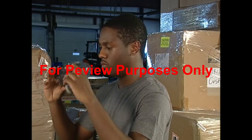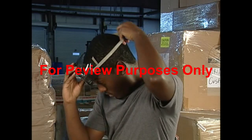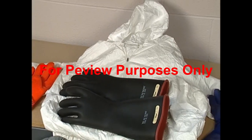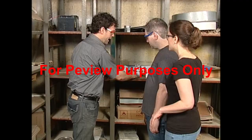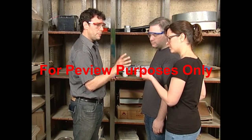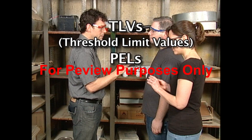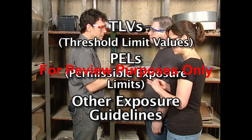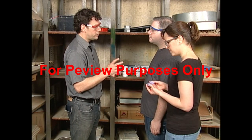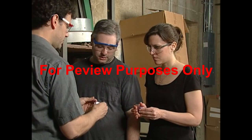For eye protection, you may be directed to wear either safety glasses with side shields or safety goggles. To defend against skin contact, rubber gloves and other protective clothing might be specified. Section 8 of the safety data sheet will also list any TLVs, threshold limit values, PELs, permissible exposure limits, or other established exposure guidelines for the material or its hazardous ingredients. This information is used by your employer to determine the engineering controls and personal protection that is appropriate for the work you are doing.